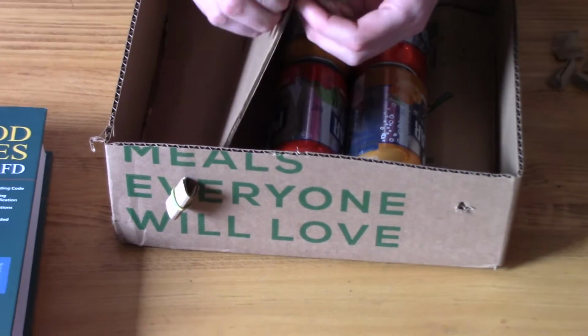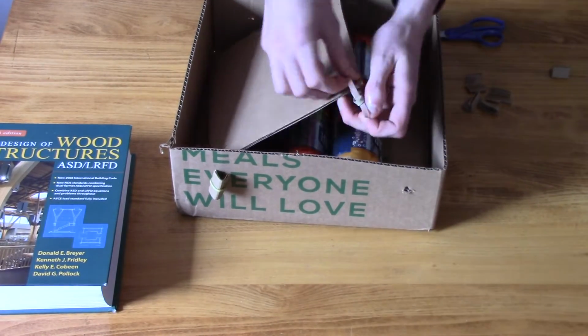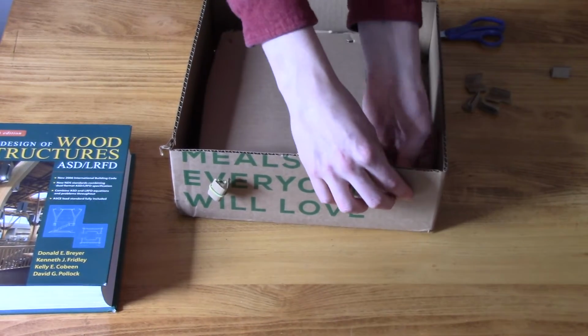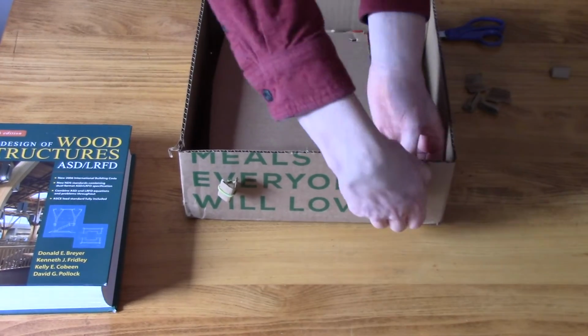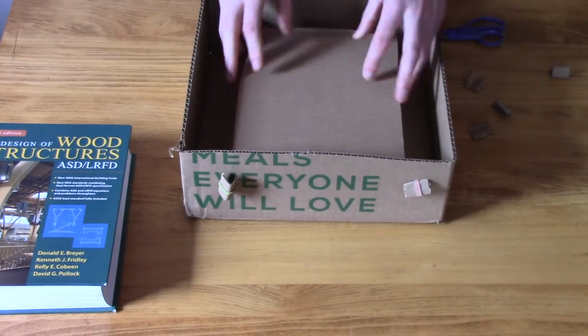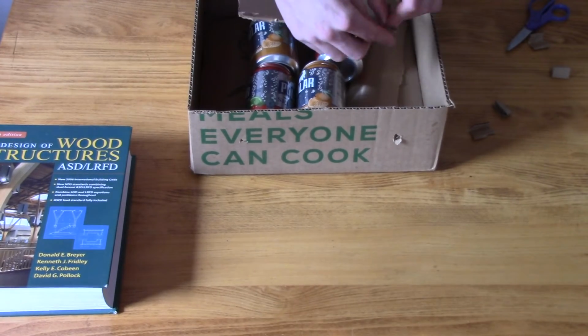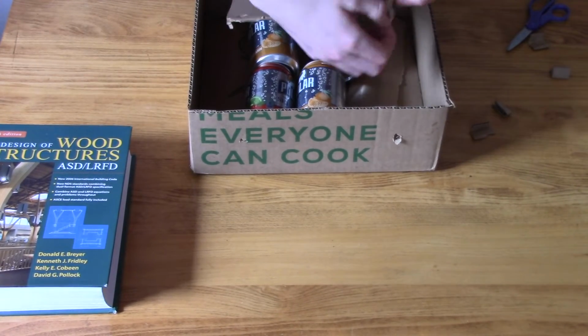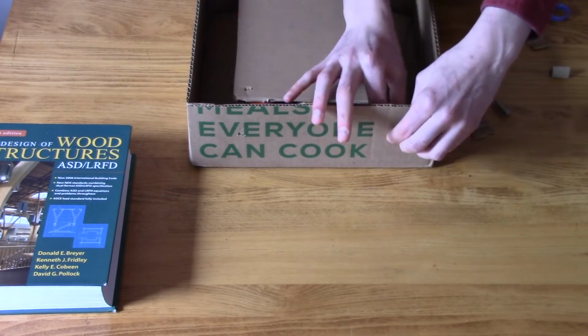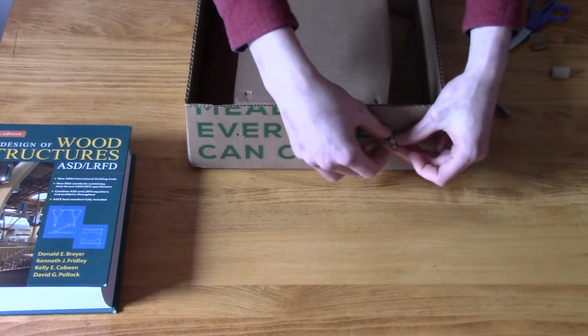A structure subjected to an earthquake experiences cyclic movement that can be idealized to be at a certain frequency. The frequency that the ground moves is determined not only by the earthquake itself, but also by the soil it rests on. Additionally, every structure has one or more frequencies at which the structure moves, which is referred to as the fundamental period, measured in time that it takes for the building to sway back and forth one time.